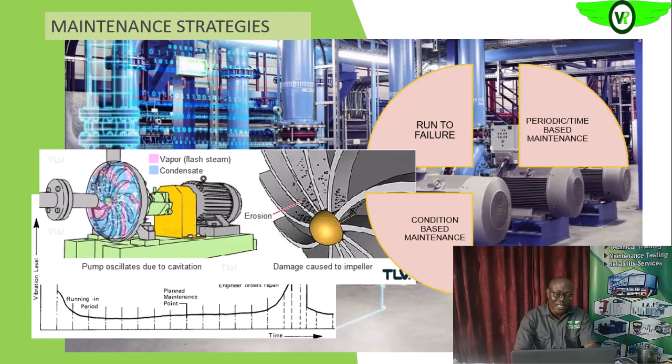Then on the front cover and the back cover, we also have bearings. We can look at the bearing temperature too. Remember, since the bearing is fixed on the housing, on that cover, whatever heat that is generated will be transmitted to that housing. So we can monitor that temperature to give us an indication as to the condition of the bearing. So if the bearing is operating too hot, which we know is not too good for that bearing, it can also affect the operations of the bearing.